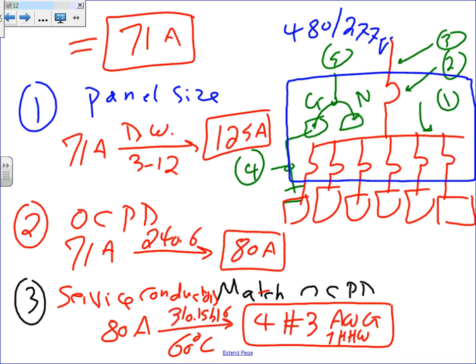THW is the conductor, and this is going to be 1.25 inch PVC schedule 80. You're expected, guys, as designers, as electricians, when you size a conductor, you can't put a conductor up in the air. You're supposed to find a conduit that holds the conductor, right? So 1.25 PVC schedule 80.